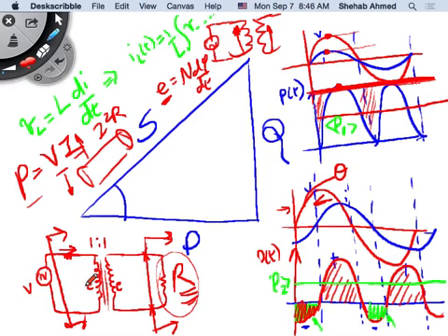And for you to control the speed of a motor, what do you do? In 338, Dr. Haytham was talking about induction motor speed control. What were you doing to increase the speed of an induction motor, for example? You're applying more voltage, higher frequency, right? The V over F ratio, remember that? So you're applying more voltage. If you're applying more voltage and you have lots of turns that are shorted, a lot of current will flow in these shorted turns and cause a lot of current to flow from the input as well, because the input source now is seeing a larger short circuit, is seeing less impedance. So maybe the input power supply could not cope because of some of the stator turns being shorted, right?